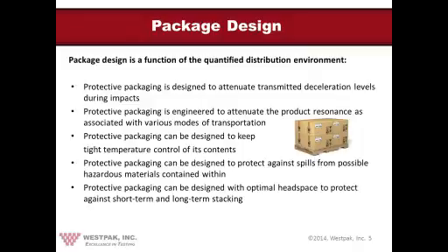Unlike shock, which is a matter of probability, vibration is guaranteed to occur 100% of the time when you ship a package. The cushion system should again function to attenuate the vibration input at the resonance of the product. The resonance is the frequency at which the response of the product is highest compared to the input, and is typically where damage occurs. A poorly designed package can actually amplify the resonance of a product, which can in turn destroy it. Shock and vibration aren't the only elements to protect against.